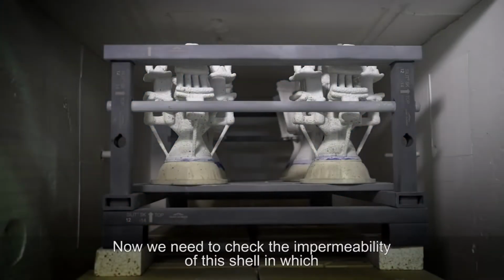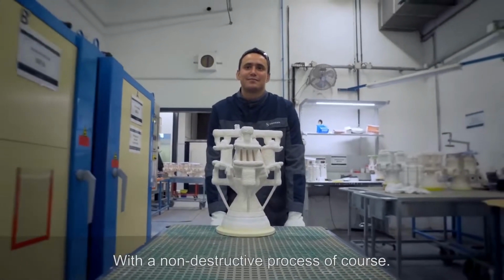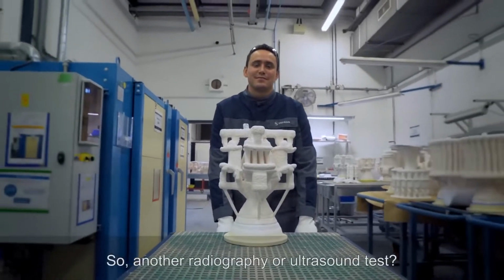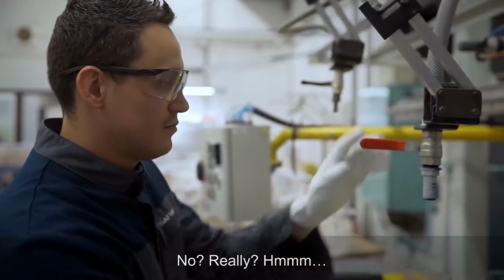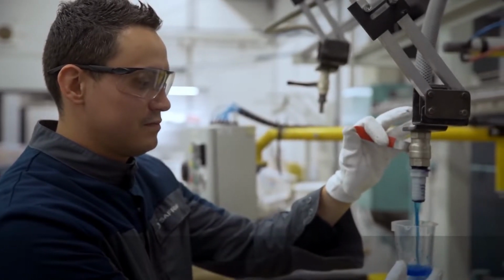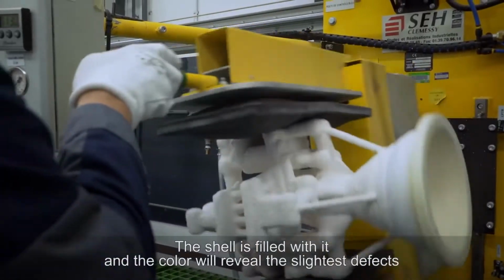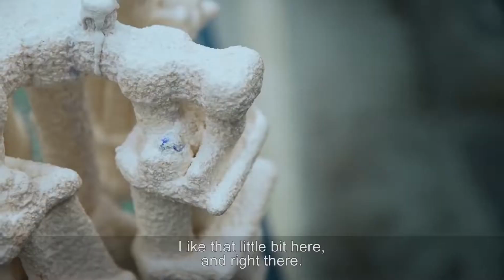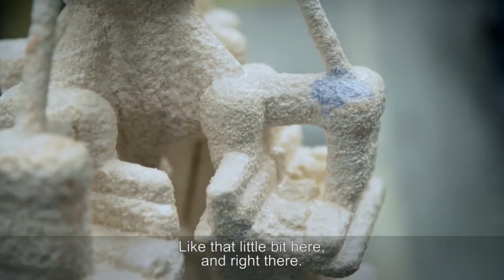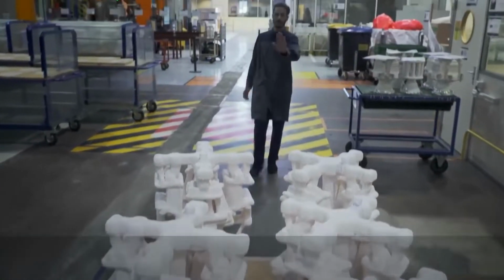Now we need to check the impermeability of the shell in which the metal is going to be cast with a non-destructive process, of course. So another radiography or ultrasound test? No? Really? With methyl blue solution, of course. The shell is filled with it, and the color will reveal the slightest defects by making them turn blue, like that little bit here, and right there. The compliant shells are then taken to be cast.